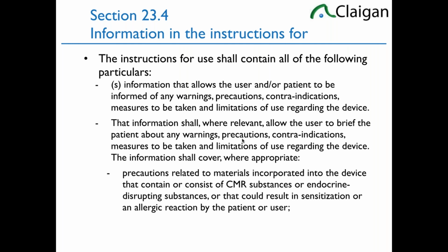Not to mention some other materials, but nickel very heavily gets brought into play as a dermal sensitizer. About 10% of the population is heavily allergic to nickel. This brings in stainless steel to a certain extent if it has any nickel migration. Stainless steel very commonly has nickel. You have to make sure it's high quality so it doesn't have nickel migration, but it can if it's done improperly. So you're looking heavily at latex and nickel and potential chromium and some other allergic substances or sensitizing substances.